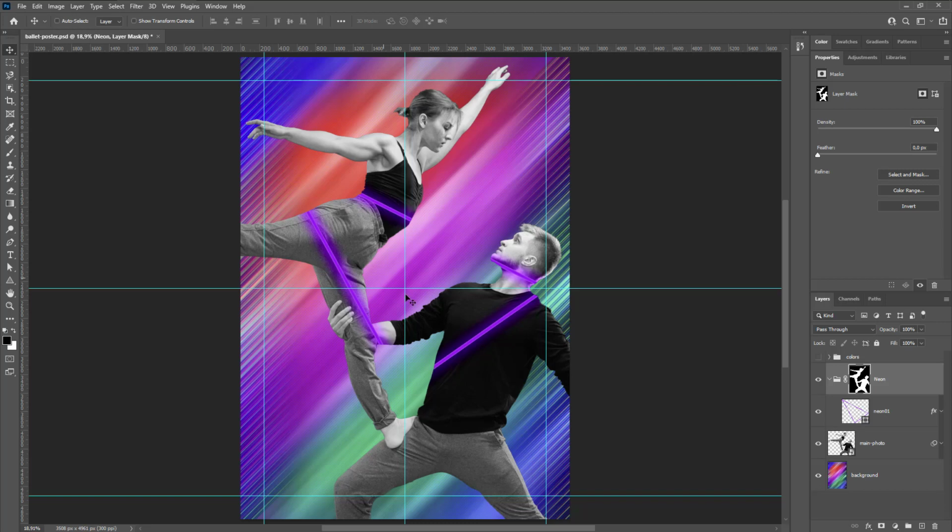So now, as you can see, it's completely wrong, of course. So we have to kind of erase some parts. So for example, I need to invert, let's try to invert this thing, and you see, oh, now it's behind my object, okay? By the way, to invert a mask, select the mask, Control I, then you are going to invert. If you select the mask and hit this button here, you will see the same result, okay? This is invert as well. And it appears because you selected the mask, of course.